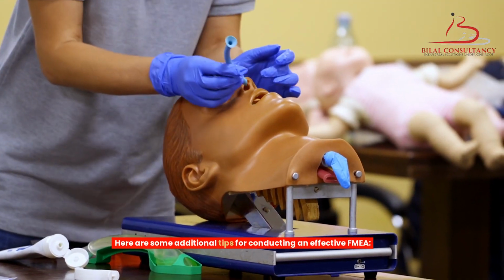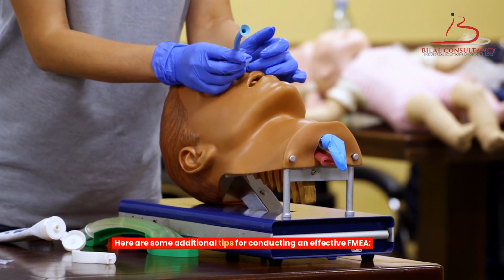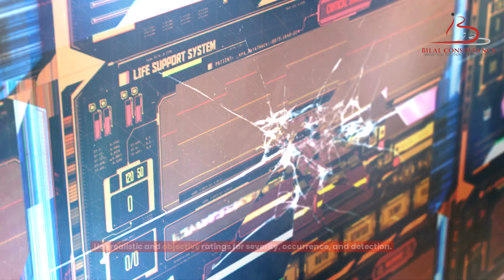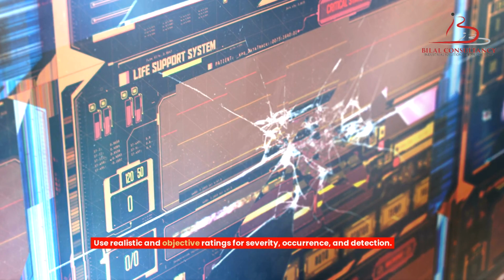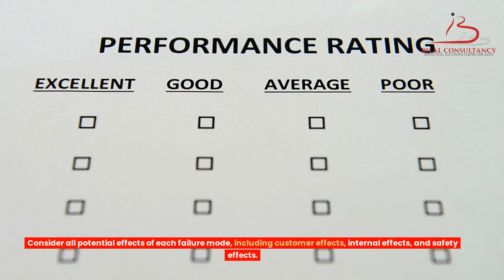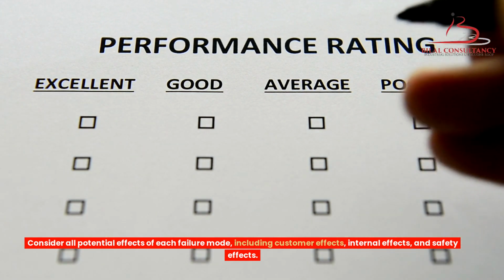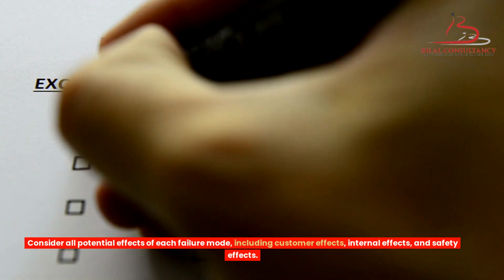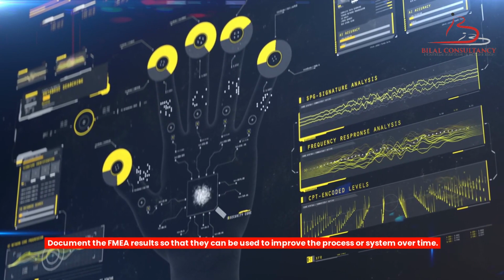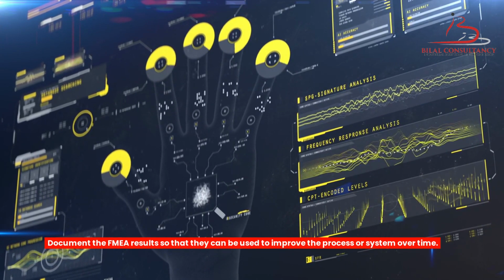Here are some additional tips for conducting an effective FMEA. Be specific when identifying failure modes. Use realistic and objective ratings for severity, occurrence, and detection. Consider all potential effects of each failure mode, including customer effects, internal effects, and safety effects. Document the FMEA results so that they can be used to improve the process or system over time.